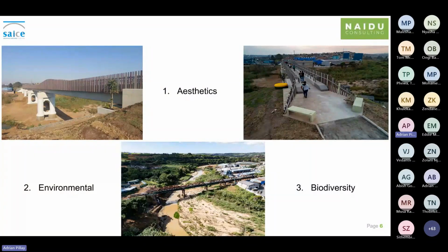By retaining and reutilizing the existing substructure, environmental triggers were avoided, as working within the watercourse was not necessary, thereby negating the need for formal environmental authorization or a water use license. The planter boxes were incorporated into the retrofitted pier extensions, enhancing both environmental value and visual harmony with the surrounding landscape, contributing to the ecological value and urban greening effects.